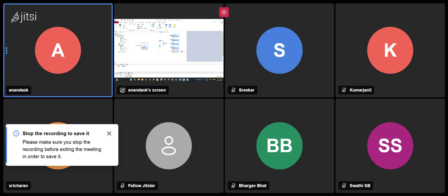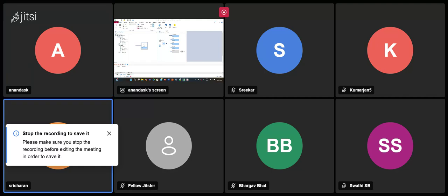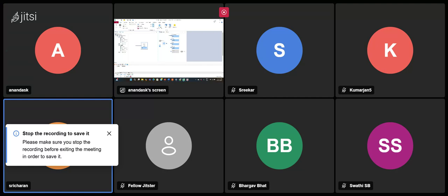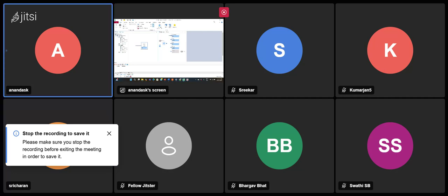So that environmental variable, you can create your own environmental variable using existing signals? Yes. We have to create it, and for every particular signal we can create it. That also we can attach in the panel, because some signals are event triggered and some signals are going periodically. So to check that, we add an environmental variable sometimes for a few signals. It's not the main reason, it's one of the reasons.